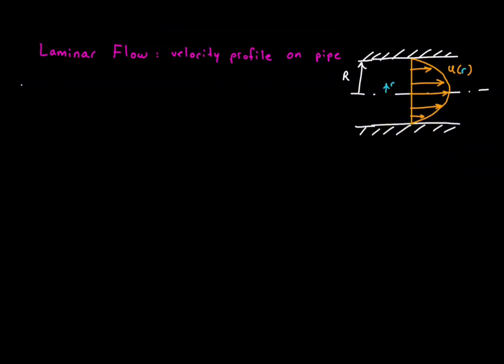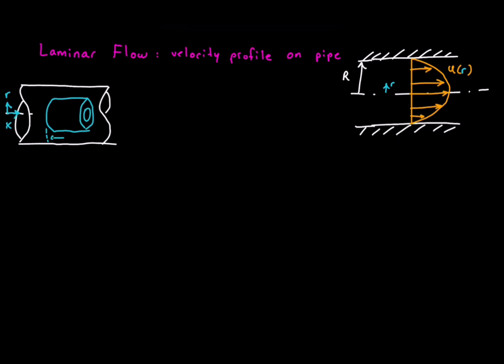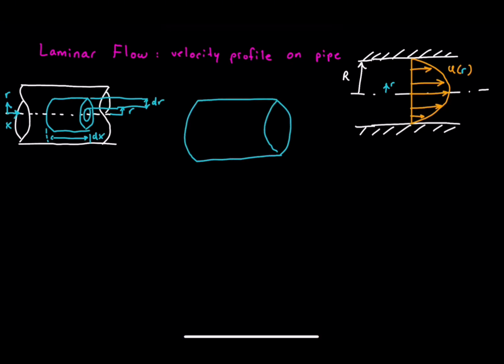First, let's define the geometry and the control volume. We are looking at steady flow in the x direction. The velocity only depends on the radial coordinate r. To derive the governing equation, we take a differential cylindrical control volume with radius r, thickness dr, and length dx. The flow direction is x, not r. R is just the direction in which stresses vary.